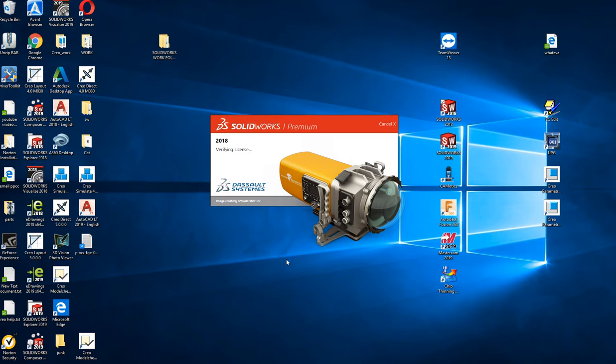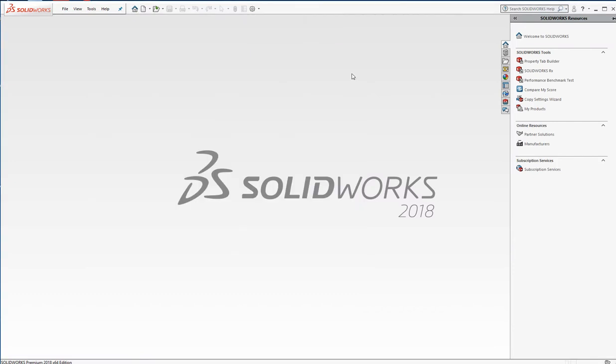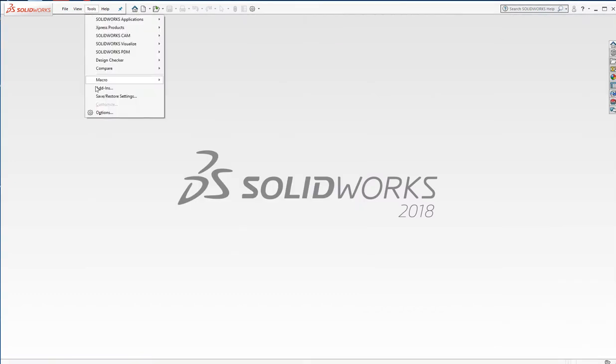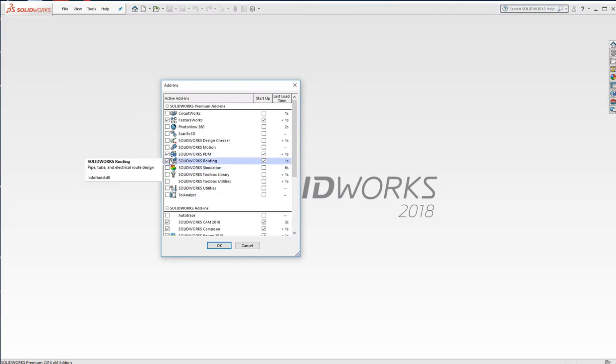Alright, our goal is to make a little pipe extension with a T on it, and it should be nice and quick. We'll try to even go into a drawing. I'll do that on a second video. But first thing we want to do, hurry up. I'm sorry, I got a lot of add-ins. Especially that's the other thing, at school right now we might not have the add-ins on, so let's check the add-ins and turn the routing on and turn it on startup.